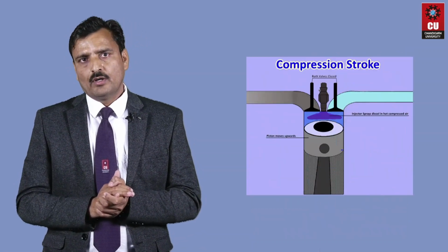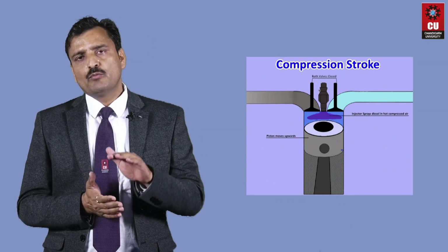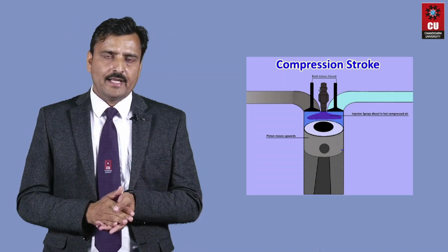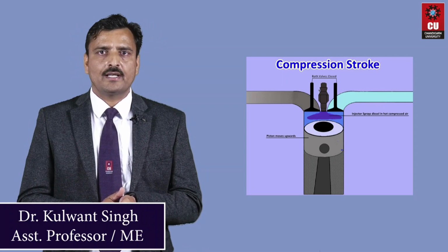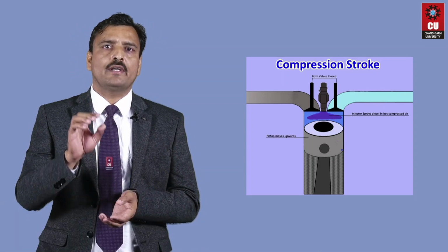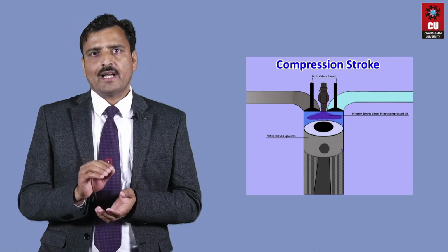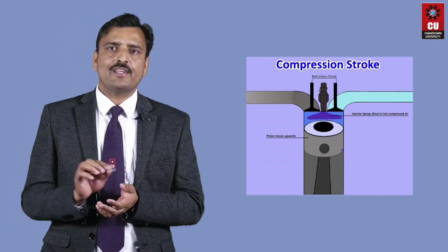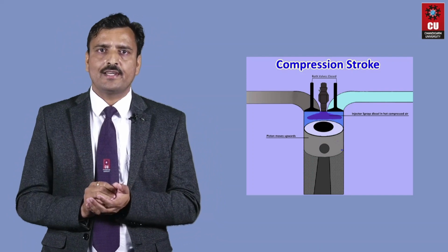degrees. In the compression stroke, the inlet and exhaust valves are closed. The piston moves from the bottom dead center to the top dead center. Air is compressed, reaching a temperature and pressure that exceed the ignition point of the fuel. The pressure and temperature of the charge increase and the crankshaft rotates about its axis about 360 degrees and it